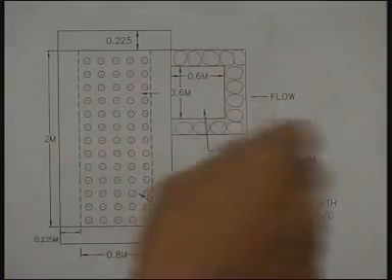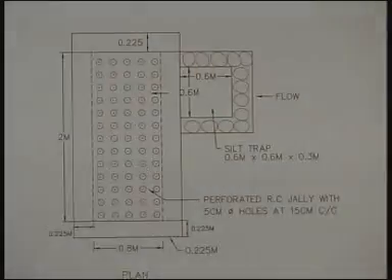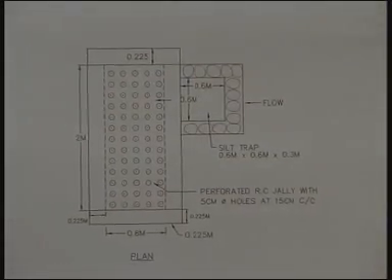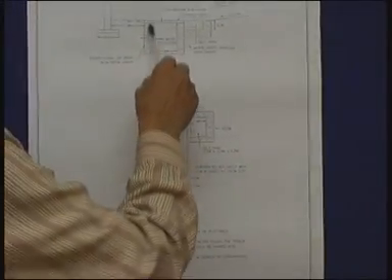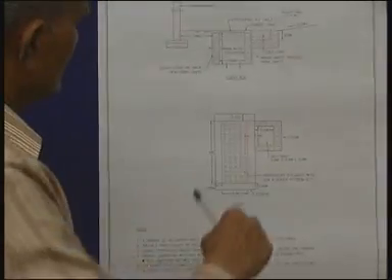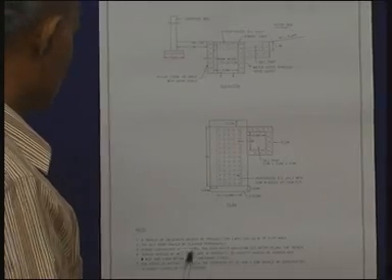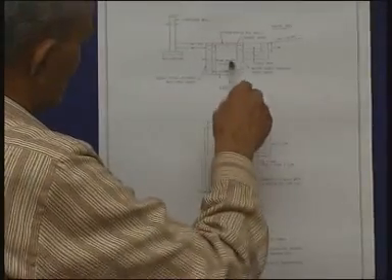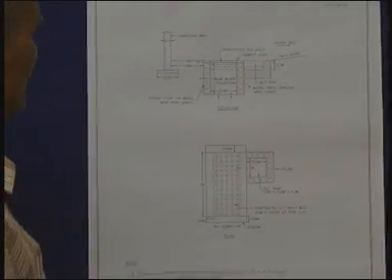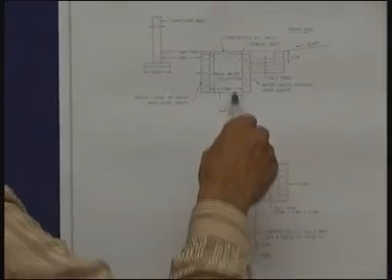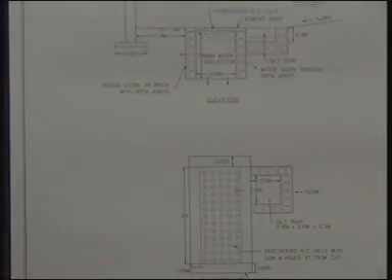And during continuous very heavy rains there may be overflow, but that would be only a rare occasion when this gets filled up and then overflows. Otherwise this will intercept and store water that comes out of a 1 inch precipitation in 1 hour, and again it seeps through. For places like Hyderabad and red soil areas, urban areas, the seepage would be quite significant and the water will disappear after a few hours.